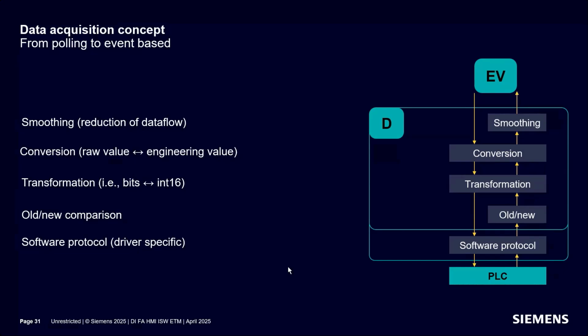And imagine a situation for alarms, for example, when you have an alarm and this is a Boolean signal that is false the whole day long. You can poll it very fast. It is no load to the system at all, only a little bit in the driver, of course, and it gets rid of these repetitive same values immediately when it receives them, through the old-new comparison.